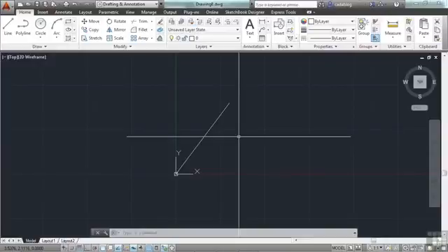And this is how surveyors will draw in AutoCAD. They will typically need to work on some sort of coordinate system. In the United States, we use a lot of state plane coordinate systems, and that origin is set at some arbitrary point in the real world. That's at 0, 0. And then they may go thousands of units away because they're usually covering large areas. And you can draw from point to point. So this is a very useful and just another way of drawing in AutoCAD.